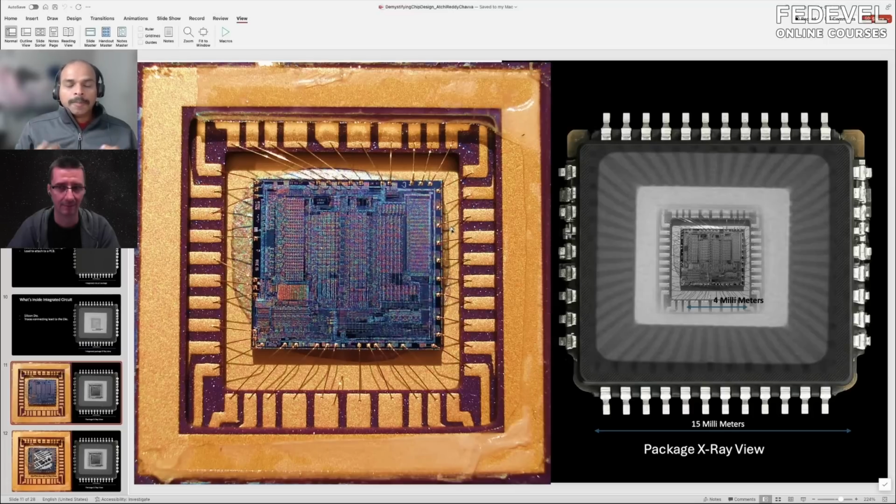The purpose of the test structures is to help debug if the functionality of the chip is not what is expected. So we probe these test structures and tell them to read the value of a particular register, and then we compare with our standard expectations.